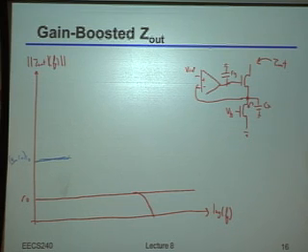And in particular, let me just draw this a little bit carefully. It'll do something, roughly speaking, like this, right? Because basically when that CX kicks in, it's just going to short out that source node, right? And so if I'm now looking, for example, out here, then indeed what should happen is that when that CX shorts out, I lose the RO on the bottom. Okay? Turns out in the limit, it would probably flatten out to something else over there because you'd get just the RO of the cascode, but don't worry too much about that. Okay? So that's indeed what's going to happen when I add the cascode in.